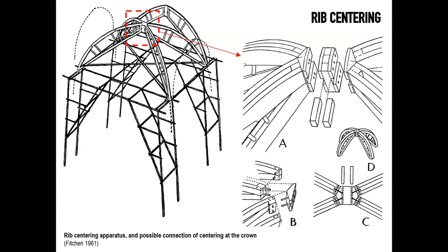Now, most important would have been the use of centering again, particularly in the rib vaults, perhaps using these systems of lagging, where you could imagine some fairly rough timber logs that would have been cut to size and reused from one bay to the next, and then keyed together with the same system of centering we discussed earlier, where two of these frames come together.